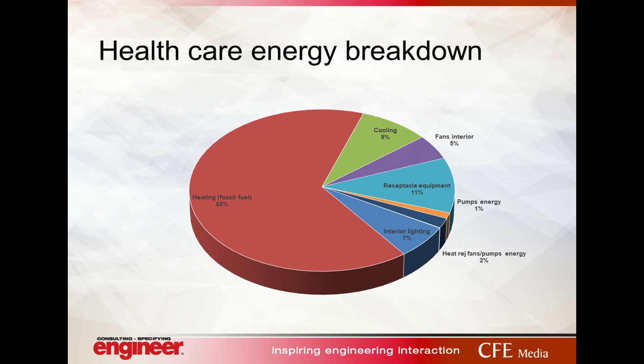In healthcare, and Jeremy's alluded to it a lot, the number one energy user is heating. And a lot of that is driven from the reheat because of all of these maintained ventilation, primary and outdoor air changes from standard 170. So we're constantly having to cool air down just to be able to heat it back up in order to maintain comfort in those spaces. So when we're looking for energy efficiency in healthcare, we're really looking for ways to reduce that heating energy because it is the biggest piece of the pie here.